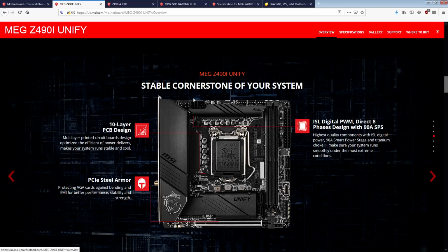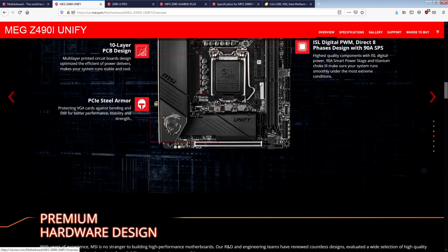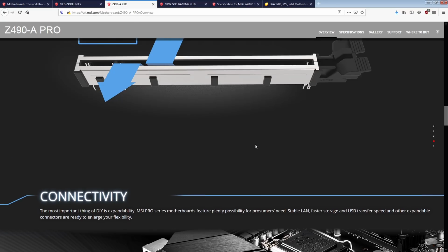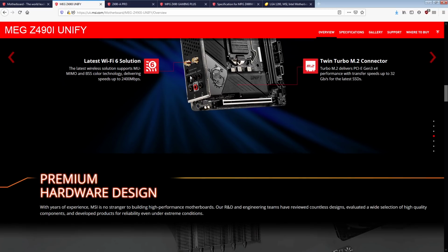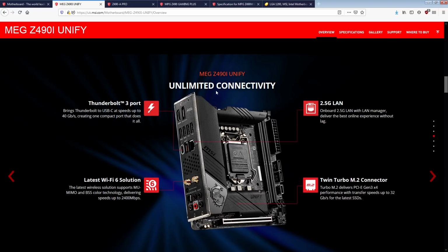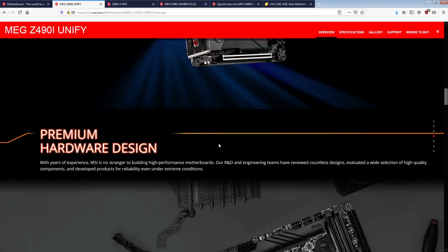For ITX, most ITX users are not going to have a 360 millimeter radiator custom loop. ITX isn't where you get the ridiculous power consumption. So for most people, the 8-pin is not really a big deal, but I would have preferred to see a solid pin power connector, especially on the ITX board. On the ATX boards, I don't care, because MSI has an obsession with adding extra power connectors. They've been using 8 plus 8-pin power connectors on boards where you can't do over 200 watts. I'm not concerned there. But here, I would have really preferred to see the actual high current version of the connector.